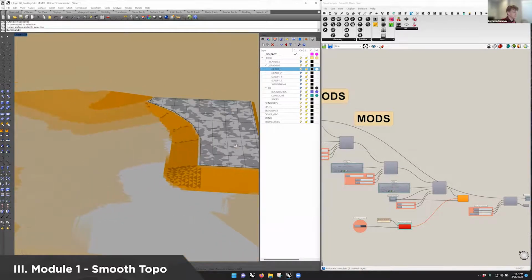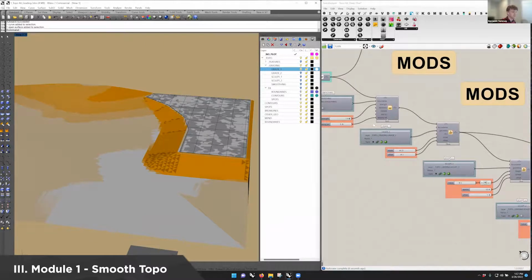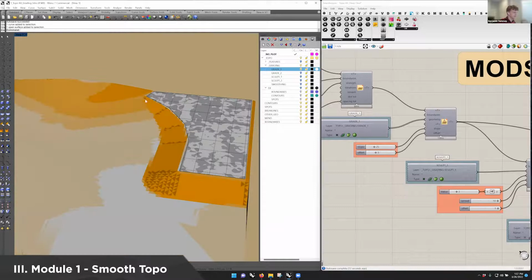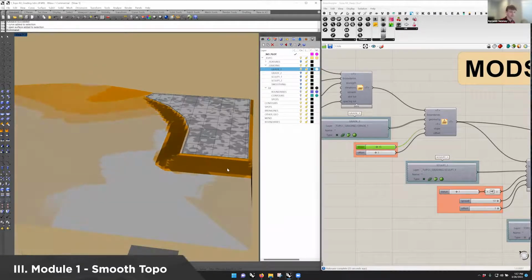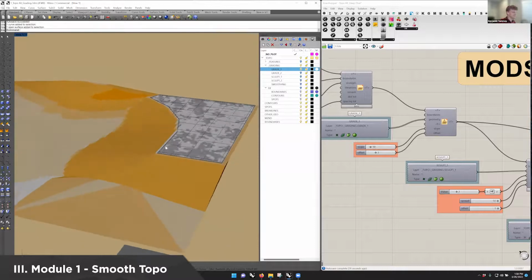you'll see what Chris was talking about: it finds that piece of geometry, and right now we have it defined as an offset of 3, so it's taking the edge of that surface, offsetting 3 feet, and then it's grading away from that at a 25% slope. If I change that slope to 35, it will make the slope steeper and grade away still. I could even change it to 10, and it will grade away to a much wider reach.